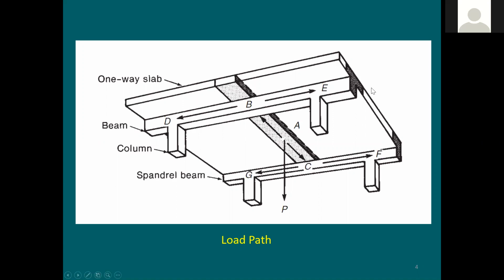I know the slab is gonna be extended for many feet right and left, but if I'd like to do a reasonable design for the slab, I'm gonna be taking a strip, let's say for the width of 1 foot only, and do the design on this. And then the rest of the strips right next to it are gonna be very similar, identical to this strip. So let's say I'm gonna come here, take this, design it, put this amount of reinforcing in there. Whatever you put in this foot, you just repeat it, because this is gonna be a good representation for the remainder of the slab.